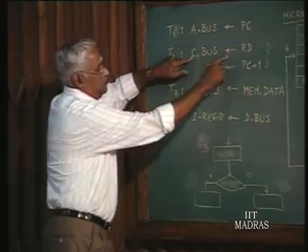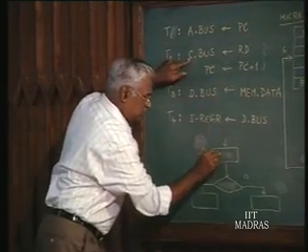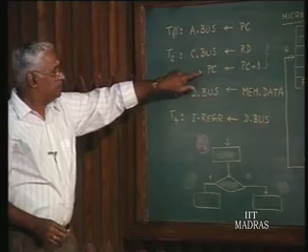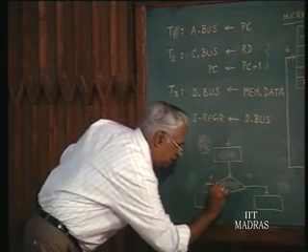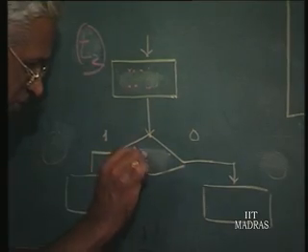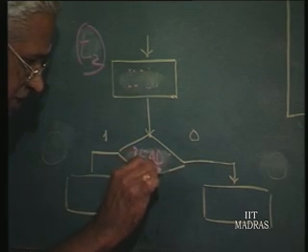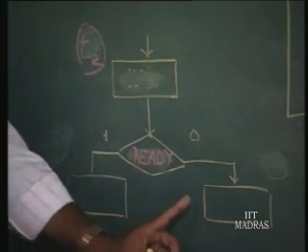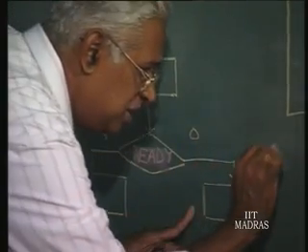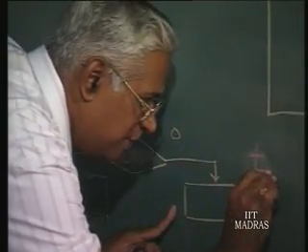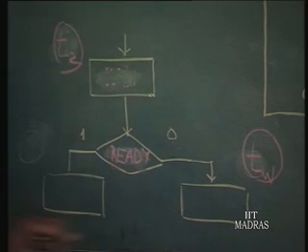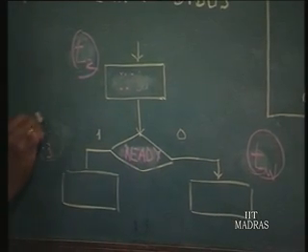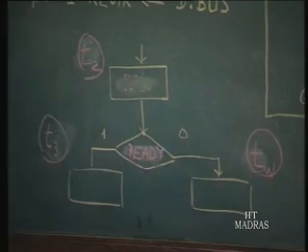There are two outputs here. These are the two outputs. And then ready is the input that is being checked. If it is 0, it waits, it stays in the same state. If it is 1, it goes to the next state, T3, which here corresponds to this.